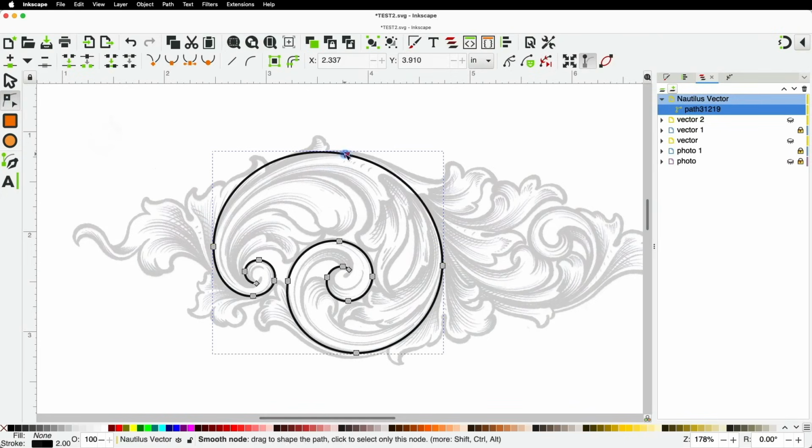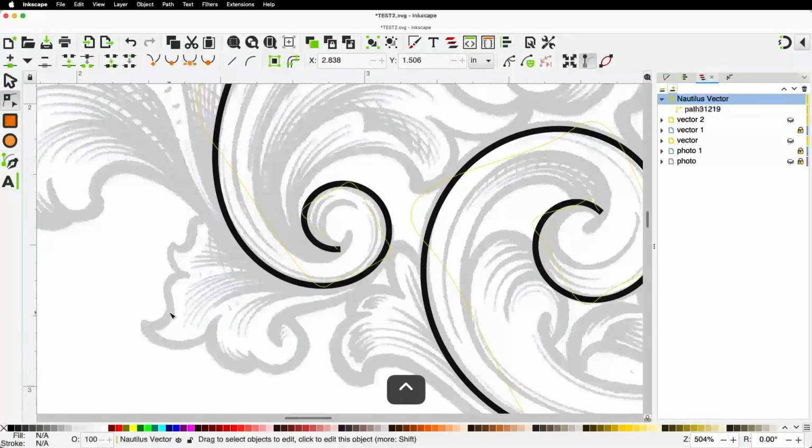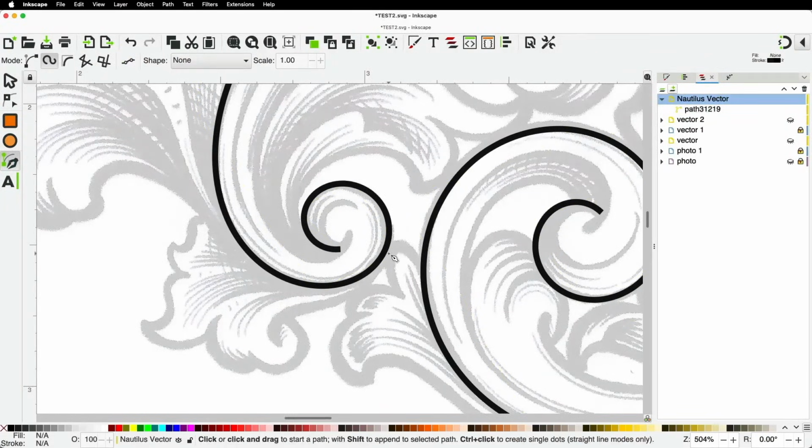Now, I think I showed you this before. But sometimes this node needs to come back around closer to the origin in order to get the shape that I want there. This is a good way to test your existing drawings to see if they're actually smooth and drawn accurately. Okay, and we can continue drawing some more. Choose the tool again. Here's a situation where you need extra points. When you have a sweeping curve coming into a tight curve, you will need to treat the tighter curve like its own little curve, which requires generally 3 points. 1, 2, 3.